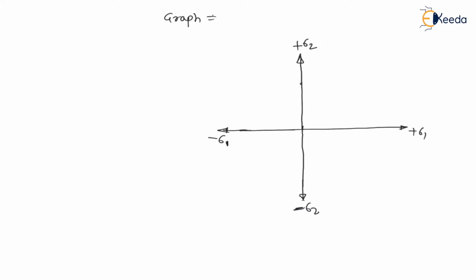Now for this theory, we are drawing the graph and we are considering ductile material. For simplicity or for calculation, we are considering ductile material here. For ductile material, the strength is corresponding to the yield point, that we already know, right? Now the theory for 2D loading is sigma 1 minus mu sigma 2 is equal to SYT divided by factor of safety.